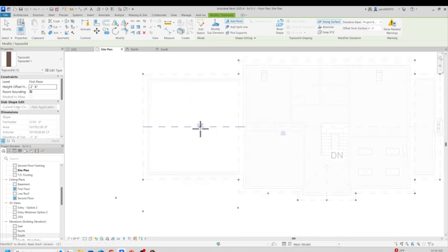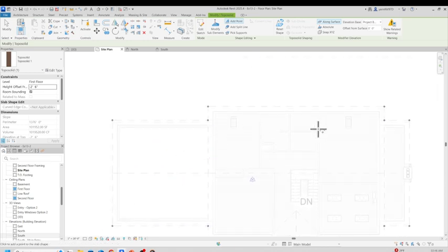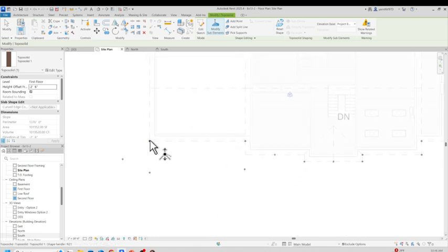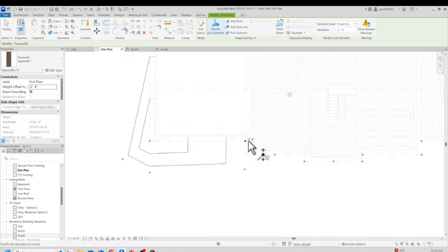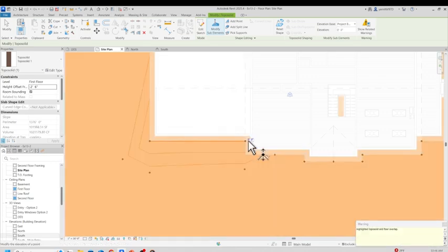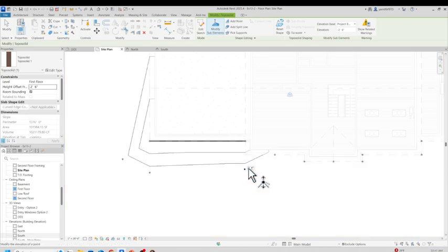Okay, so I got all these points. Let's just go ahead and fix this, and we'll add more points. So I'm going to click modify, modify element right there, and that will allow me to change this. Look at this. When I click on it, it will show me the elevation -2 feet 6 inches because that's where I set it up. So I'm going to make this a 0, 0, enter, and I'm going to make this also a 0, enter. I want to be 0 right here also, so my pad looks okay.